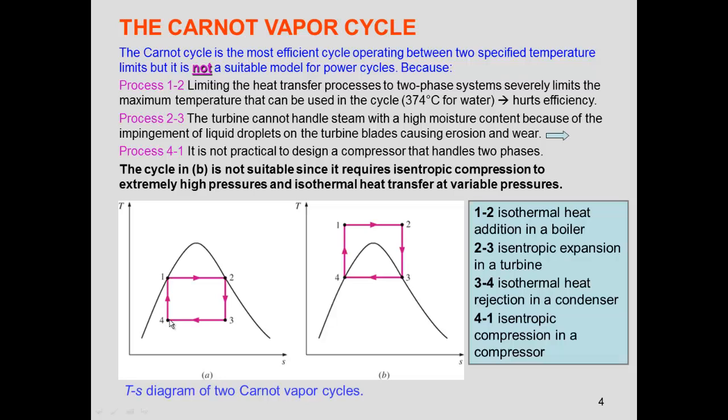two phases. Here we have a mixture of vapor and liquid, and just remember what happens at your home when you have air in your pump. You need to purge it, you need to take out the air, otherwise the work the pump does will not compress the water, but compress the air inside. So this is a problem. We don't have pumps that can pump two-phase fluids effectively.